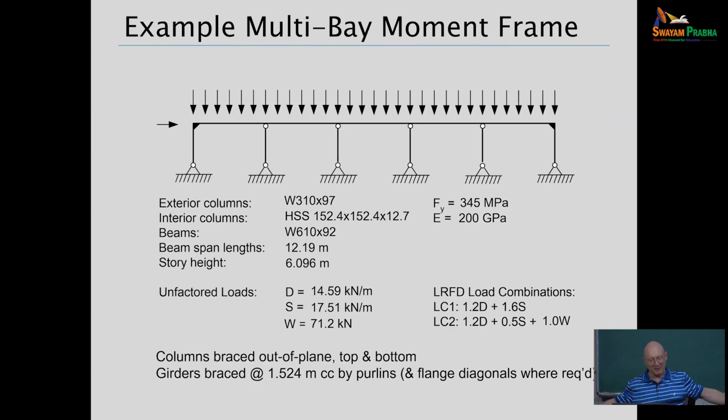It's a very wide frame, and so it would be very expensive to span the entire interior here with a clear span portal frame. If we can drop small columns down to take gravity load out of the roof, then that's going to be much more economical. So plenty of building footprint out there has frames that look like this.